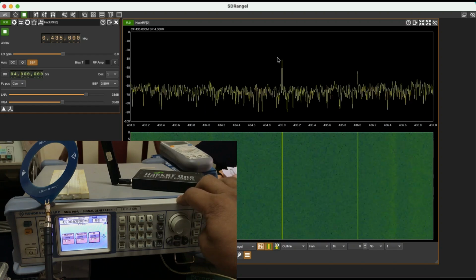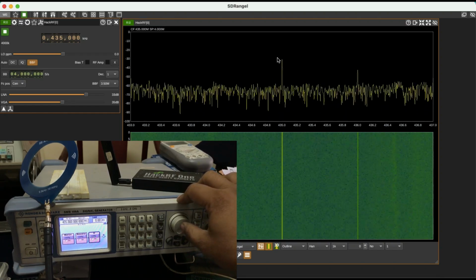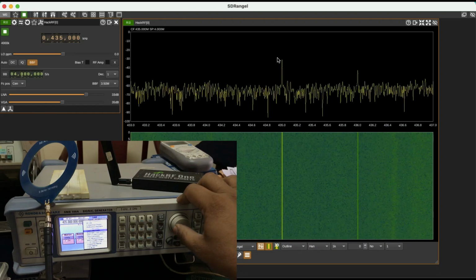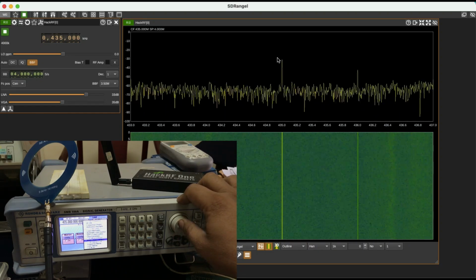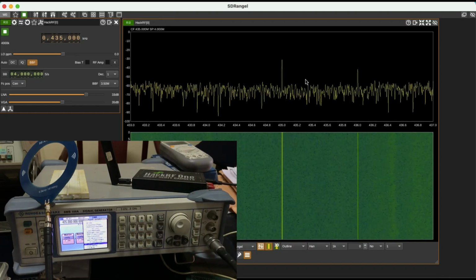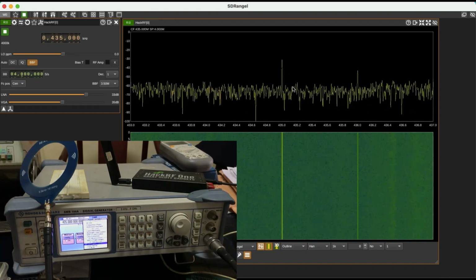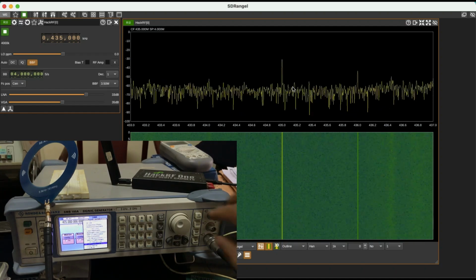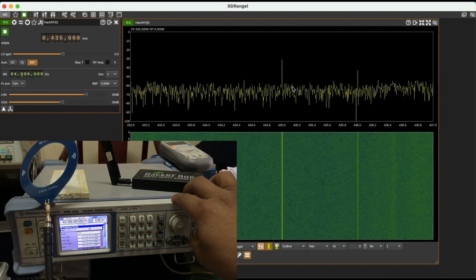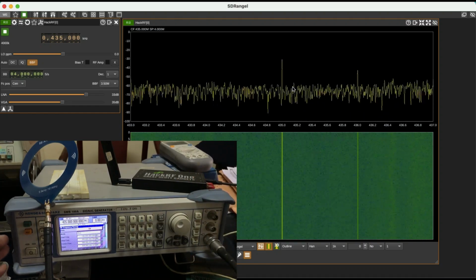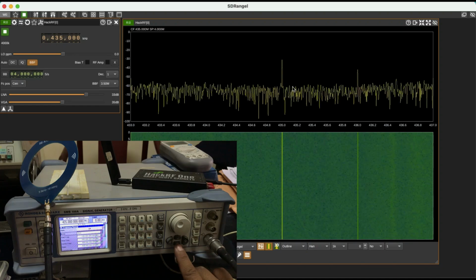All right, when you go to an RF configure block, just push it in. You will see different levels. You can do level of attenuation and things like that. Let's do a frequency sweep, one of the applications, so we can visualize this frequency sweep using our HackRF. Once you do a frequency sweep, let's click on it, and I'm going to leave these as is. Let's just read off what is there.